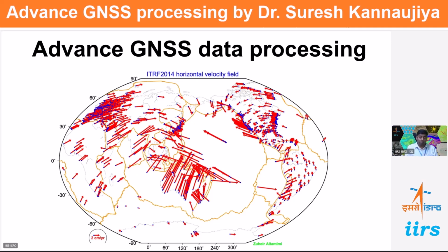Then we can think of millimeter accuracy, because there are many internal factors of importance, like the phase center variation in the antenna. If the phase center variation is less than 1 millimeter in both horizontal and vertical, then the capture of these electromagnetic waves at particular frequencies like L1, L2, L5 will be accurate.